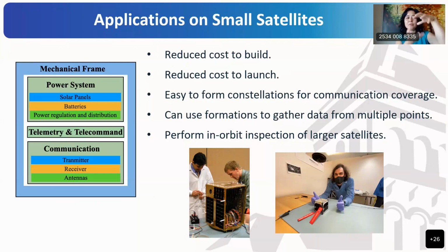And meanwhile, powering all of these with just the solar cells puts a limit on the power. Therefore, we wrap solar cells everywhere possible on a small satellite. So basically, it leaves no space for an antenna. Even if you want to just put a deployed wire antenna, it will still pop out from somewhere. So if we can integrate antennas with solar panels, that will help us tremendously to reduce price and increase feasible science payload. And of course, this can also be used for larger satellites.